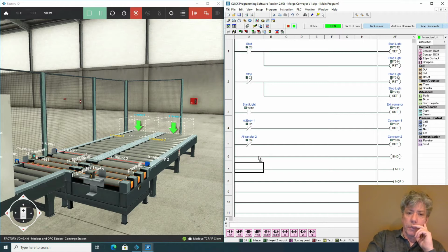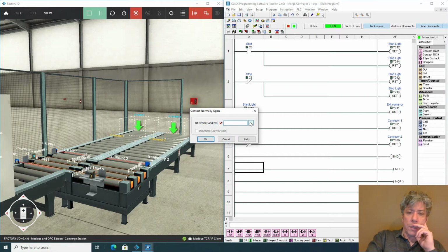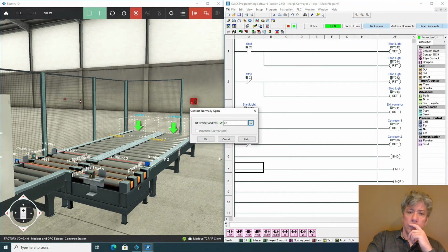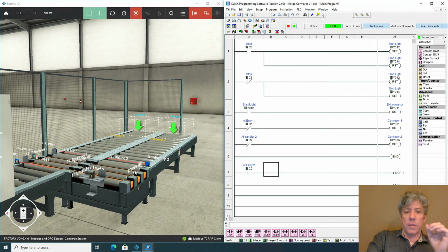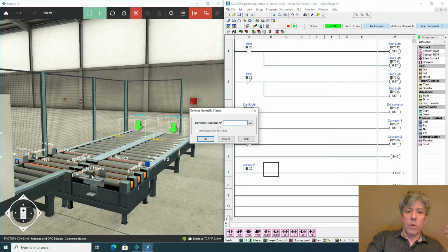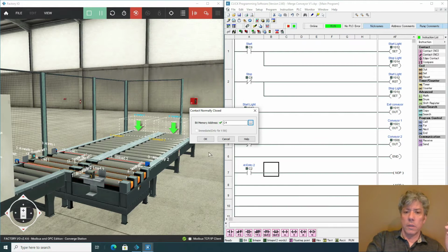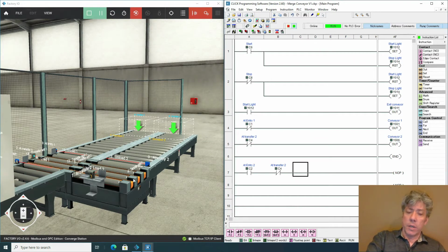Well, all right, if at entry 2 is true, if there's something here, but there's not something at transfer 2, that's the name of the sensor, then what we need to do is turn on transfer conveyor 2's rollers and get something in there. So remember I said that the transfer rollers will be turned off and on.